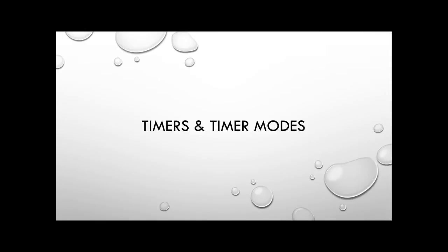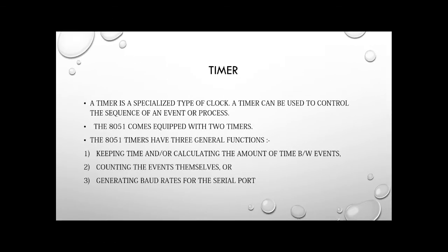Let's discuss timers. A timer is a specialized type of clock, and it is used to control the sequence of an event or process. As we can see, the 8051 is equipped with two timers. The three general functions of timers are: number one, keeping time or calculating the amount of time between events; second, counting events; and third, generating baud rates.